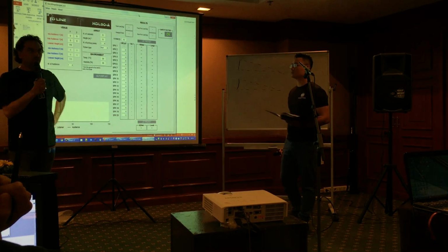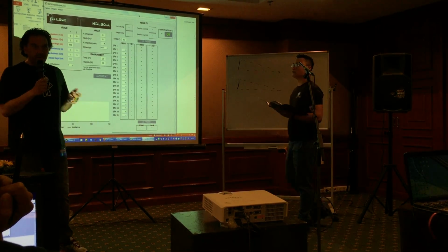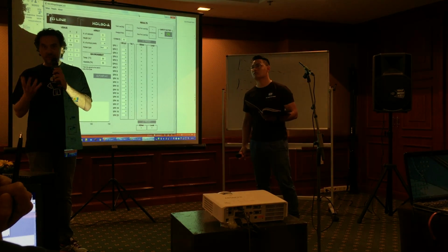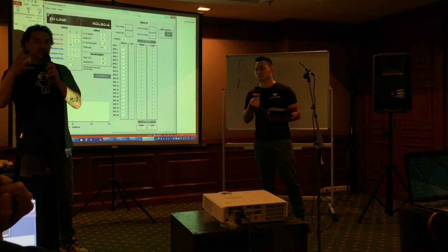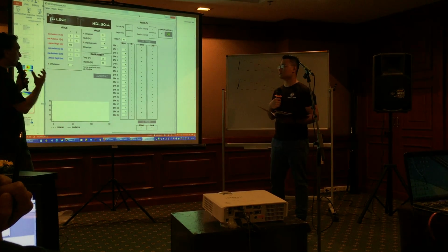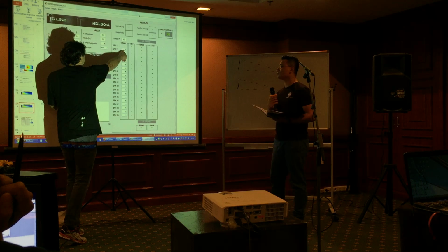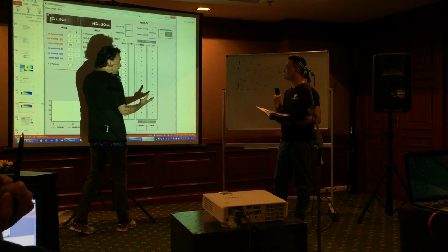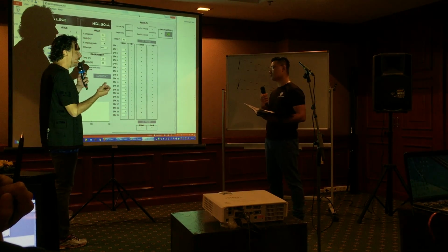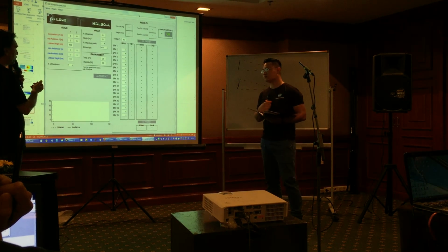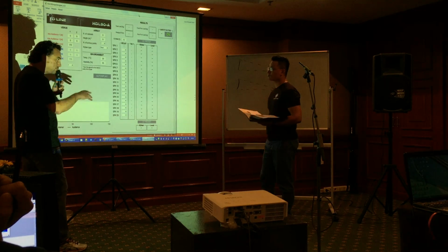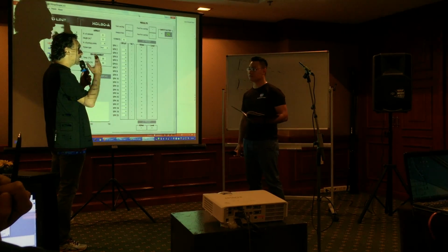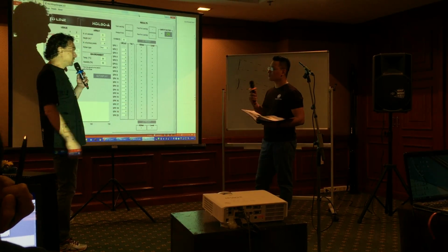Because of course, with EaseFocus, we can make a complete acoustical prediction with frequency response, with dB SPL, etc. With Shape Designer, we can achieve only the angles and the safety factor. So we do not have too much data with the Shape Designer. We have enough data to mount the system, but not the prediction of the coverage.